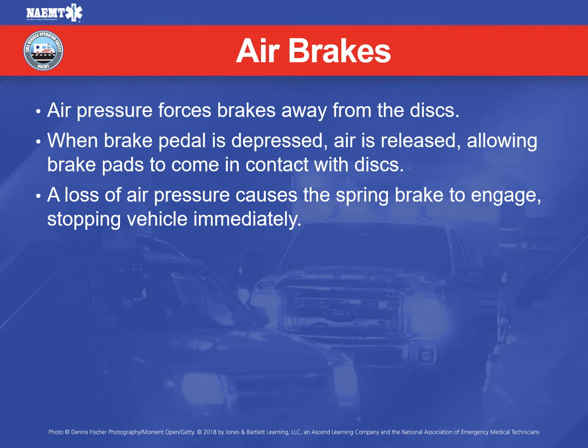Air brakes have the same task as hydraulic brakes, but work a little bit differently. Unlike hydraulic brakes, air is forced into the system and keeps the brakes from grabbing the rotor. When the air is released, nothing holds the brakes back and they engage, grabbing the rotor and stopping the vehicle. When hydraulic brakes lose fluid, the vehicle has lost brakes and cannot stop. When air brakes lose air, the spring brake engages and the vehicle stops immediately.